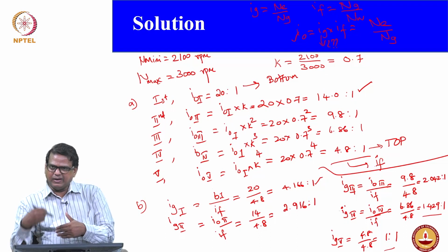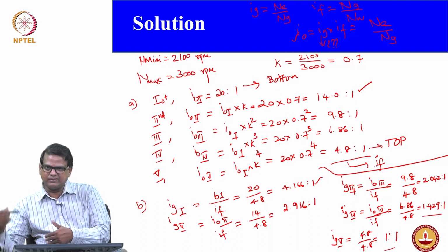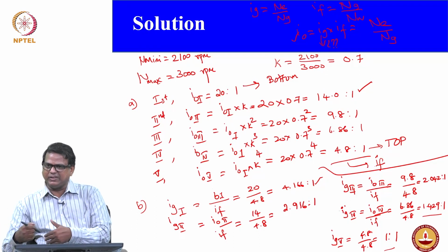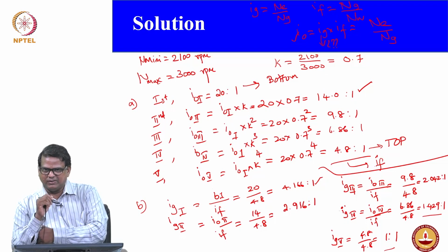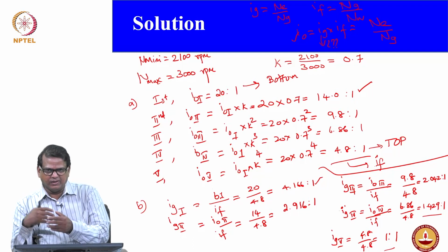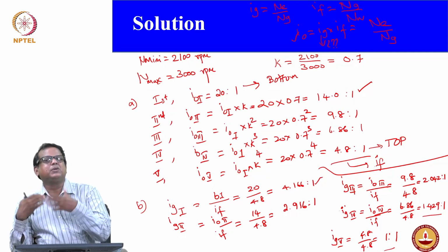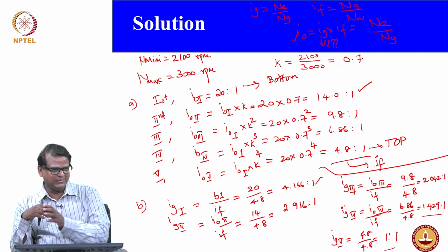From there we further reduce the speed, first, second, third and fourth. After fourth gear we are increasing the speed, to the engine speed or slightly above. With 4 speeds, the maximum is the engine speed. If you have 5 and 6, you can go beyond the engine speed, called overdrives.